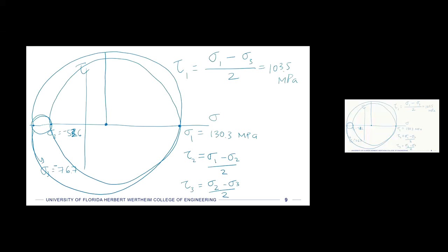But if we wanted to now draw our stress cube, instead of rotating the cube such that we only had normal stresses, we can rotate it such that we have a maximum shear stress, right, of this. And that can help us determine future things for our failure criterion. Going along with these shear stresses is the direction that you would rotate the cube in order to get these principal shear stresses, right? And if you think back to the Mohr's circle and where it comes from, let me just make sure what I have on the next slide. Yeah.